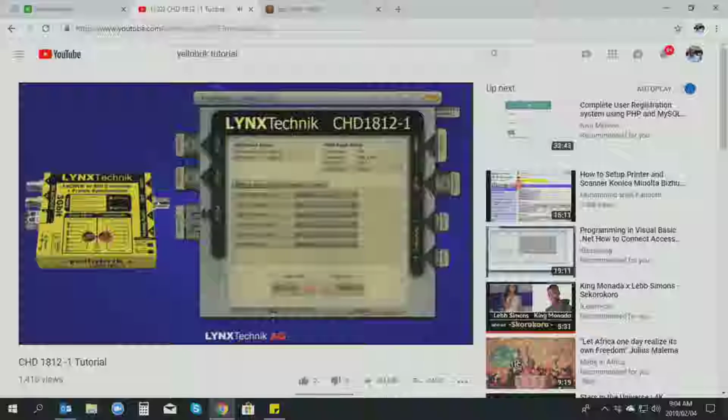What this enables you to do is connect your house reference up, your analog bi-level or tri-level sync, and it will automatically convert that 60 Hz HDMI input into a 59.94 studio quality SDI signal. And also, using the yellow GUI, there's a delay adjustment that you can make to time the SDI input into a switcher or router.